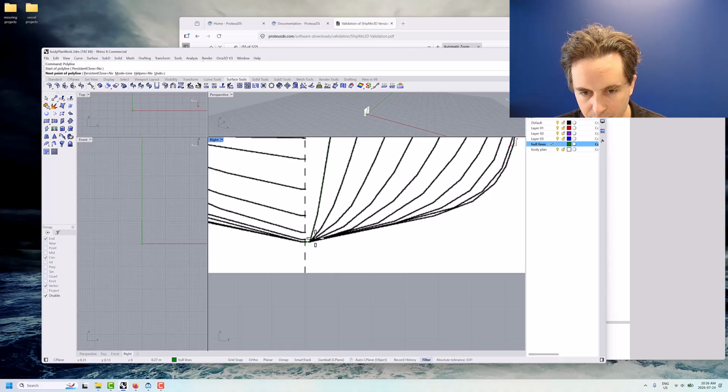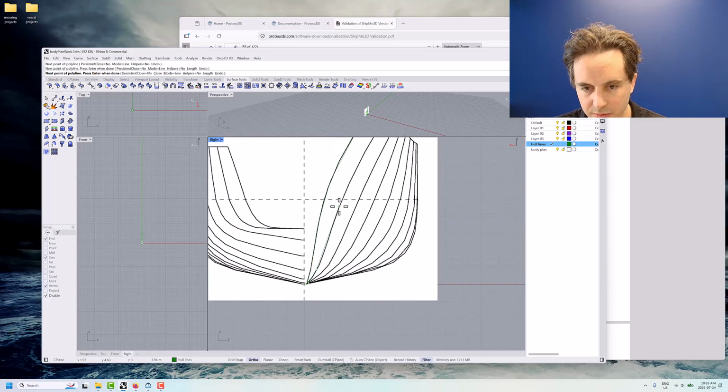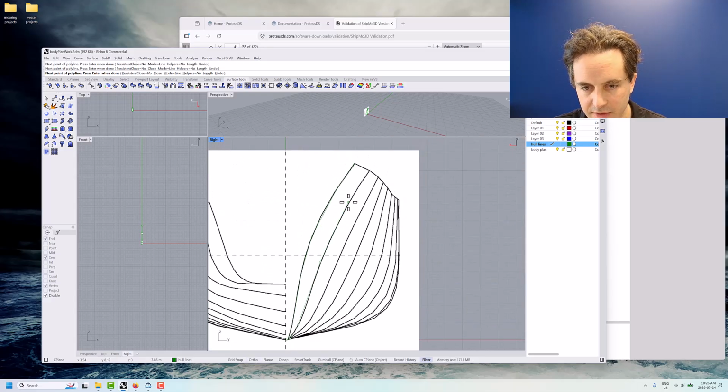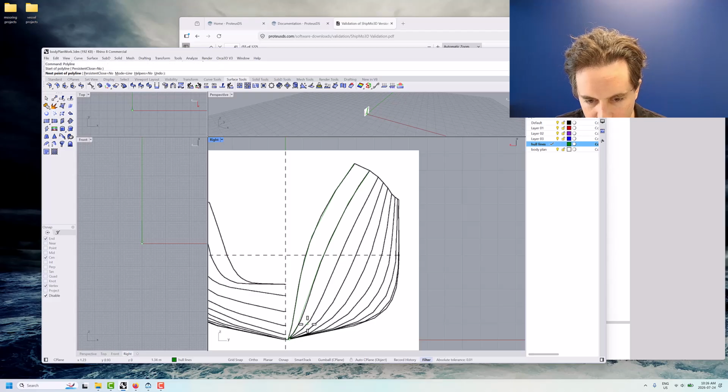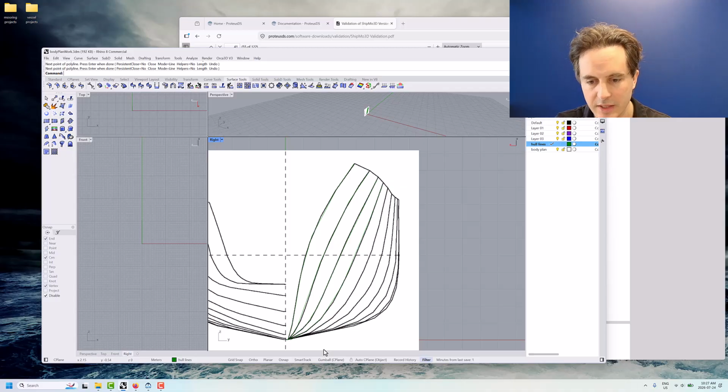Later, we're going to snap the end nodes right onto exactly y equals 0, but we'll just roughly get this going here. I found polylines pretty easy to work with, but you might have some luck working with different line model elements in Rhino to get the smoothness and the curve that you want. Of course, once you have the surface, there's a lot more that you can do.